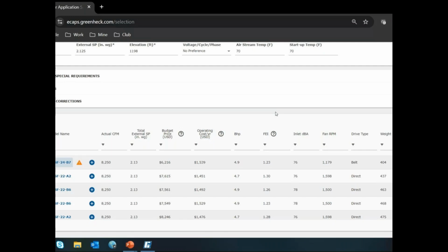If I'm sitting over the top of a solid fuel, 400 degrees for hours, then I'm starting to look at different technologies. I'm looking at moving the motor away from that airstream. I'm probably looking at a blower type fan that can handle those higher extended temperatures.